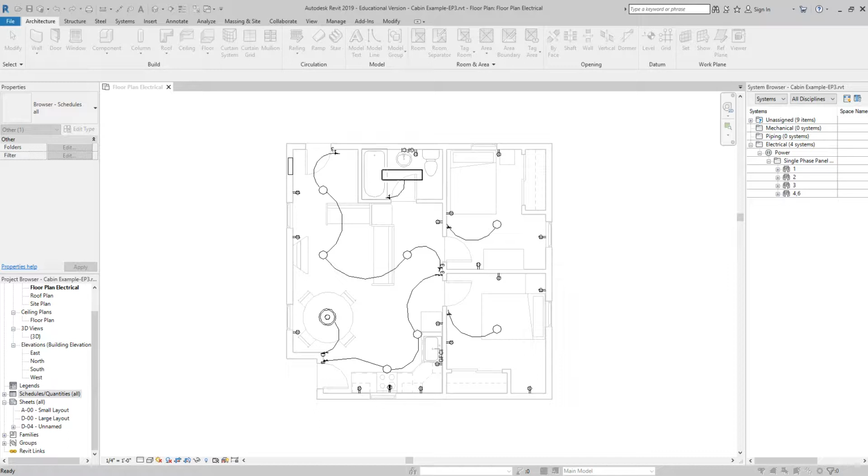The next thing we're going to do is go all the way down near the bottom and find voltage. Not voltage drop, but just regular voltage. And I'm going to add that, so I have circuit number, then voltage. I'm going to scroll up to the middle of the pack, find under the ends, number of elements. This will tell us how many things are connected in the circuit. This is where I can double check that you did only 10, or on high voltage ones, only 1. We'll put that in. The last field we're going to add is a comments field. And then I'm going to click OK.